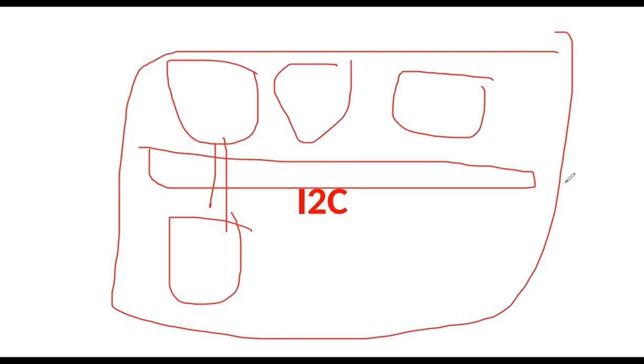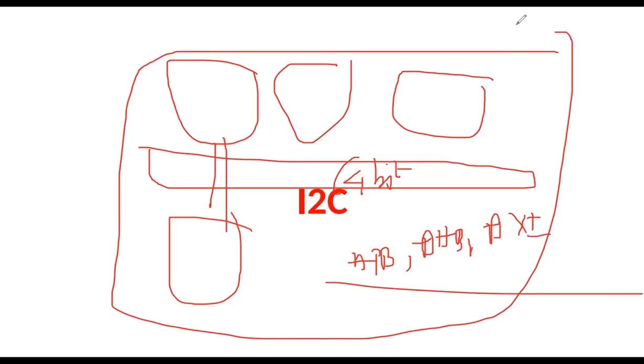That means a high speed bus, in the size of 64 bit or 128 bit like that. Those are nothing but the bus protocols we can call. Very high speed, like APB. APB is lower speed compared to AHB and AXI. APB, AHB, AXI we will discuss in the coming sessions. Today we are discussing the communication protocol, which is a low speed protocol, I2C.